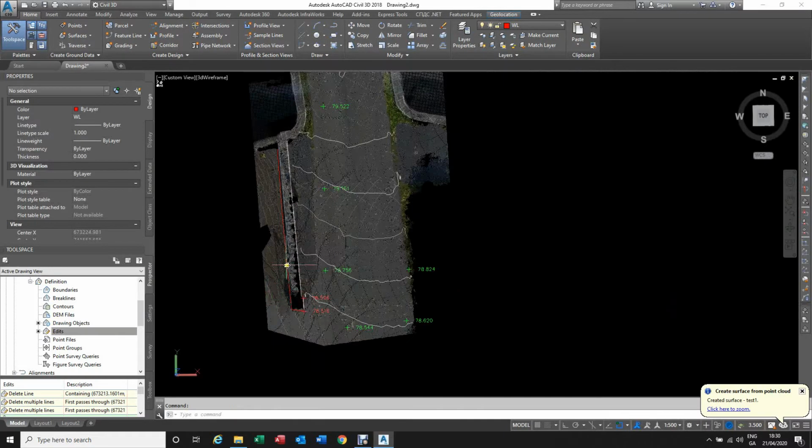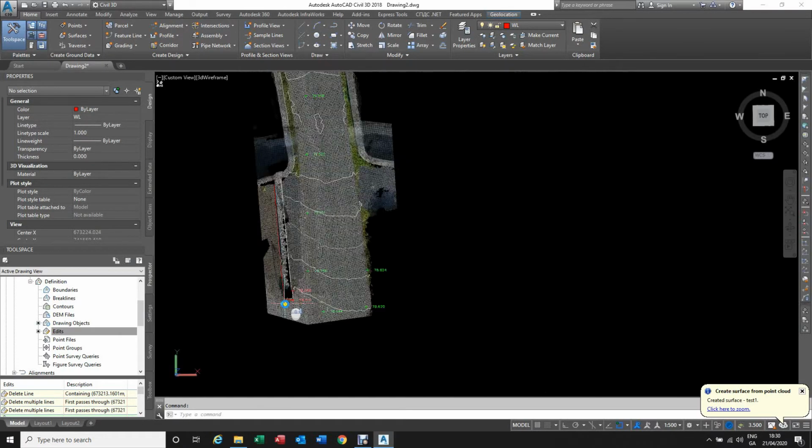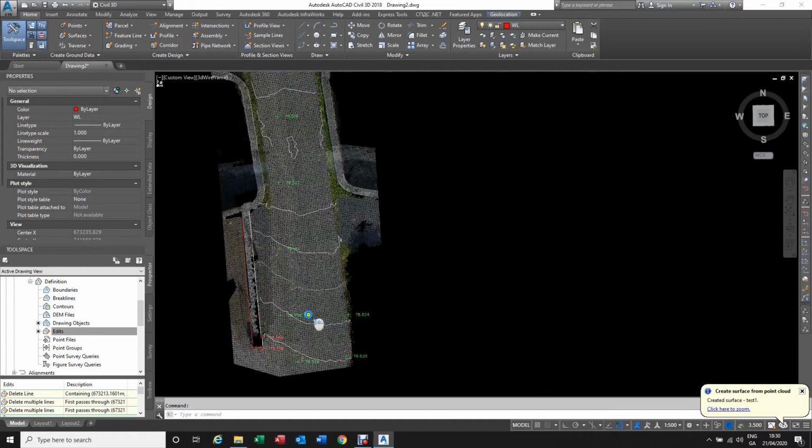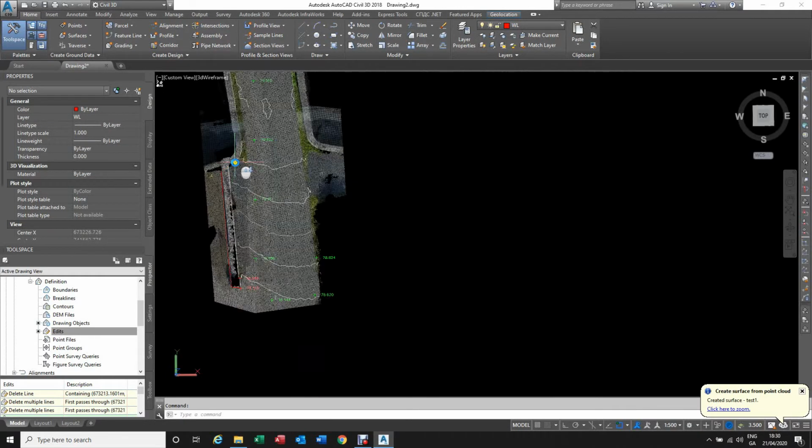So that's just a 3D polyline. That's nothing. It won't be part of the surface. It won't be a break line. It has no feature. Nothing. Just an AutoCAD line. Well, what I would like to show you is rather a feature line. Feature line has a lot of benefits. It has a lot of options.